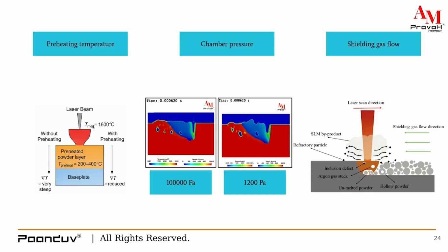You can see this example from literature we have taken. They have printed multiple coupons using the same set of feedstock, and they changed the scanning strategy from unidirection to zigzag direction and to the island directional. And they have achieved a control on the microstructure formation through that, as well as they have been able to control the porosities with these scanning strategies. The texture of the microstructure evolution can also be controlled by using these controlled scan strategies.